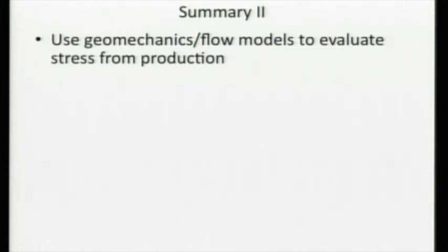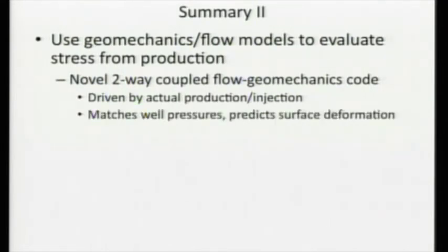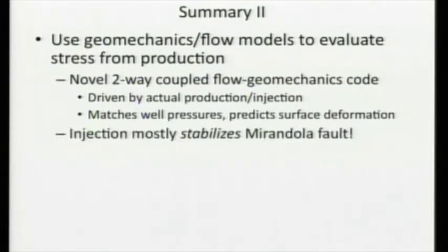We've used geomechanics and flow models to evaluate this stress from production. I think this is the first time that this has been done with a two-way coupled flow geomechanics model. We drive this by the actual production and injection, and it matches well the observed well pressures. We don't have good enough observations of surface deformation for that to be a test.